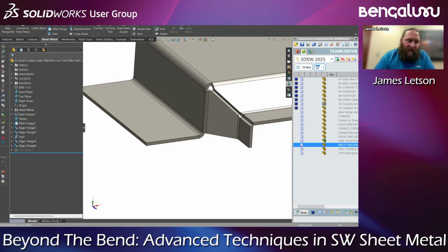As far as designing sheet metal parts, I would lean towards whatever the default bend radius is that the SolidWorks gauge tables give you. And as far as the certification, which everybody is very interested in, it's going to tell you exactly what bend radius to apply. It's not something you just have to know based on the material thickness.